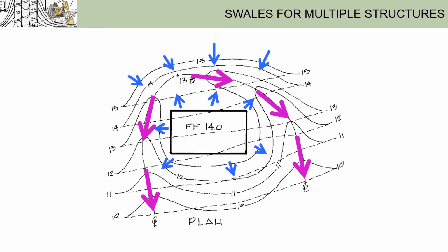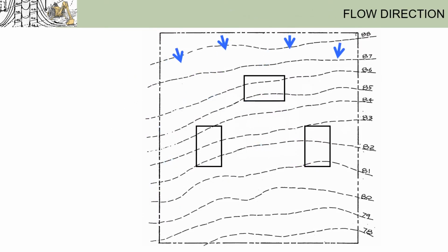As you all know now, this is the drainage directions and swale contour pattern around a single building. So what do you do when you need to grade a group of buildings? Seems very complicated, right? But let's think about where you want water to flow first. First, of course, you'd like the ground around the buildings to slope away, creating positive drainage, right?